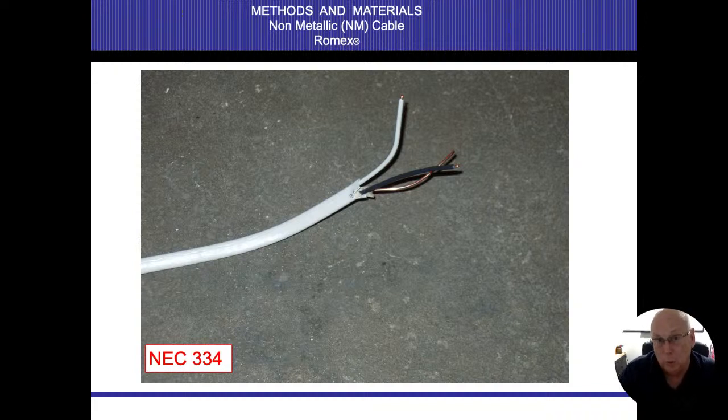I can actually use this to connect an air conditioning system. All right, it's okay to use the white wire as an energized conductor. We should relabel it as black, so putting tape on it is good, but it can be done.